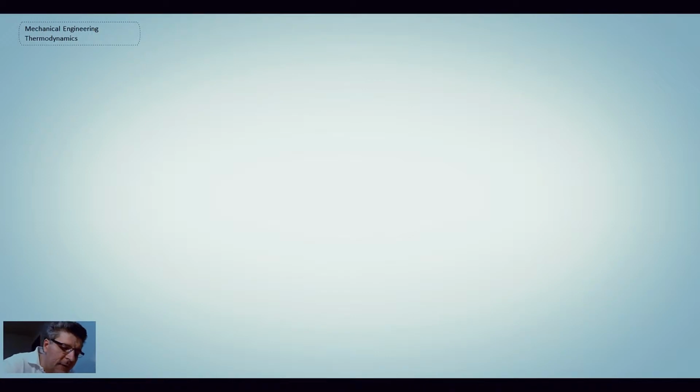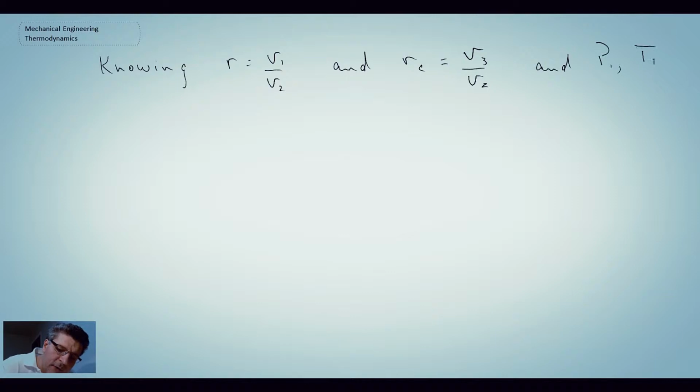Now typically what you'll know with the diesel is you'll be given information such as the compression ratio, and you may also know the cutoff ratio for the engine. And quite often you'll also know atmospheric pressure and temperature, so P1 and T1.